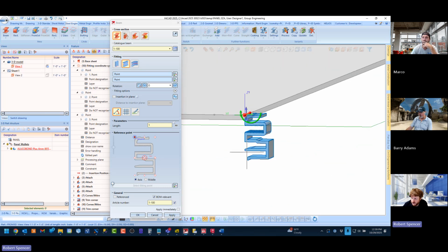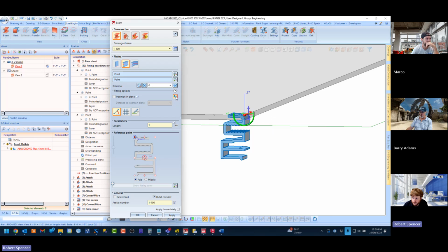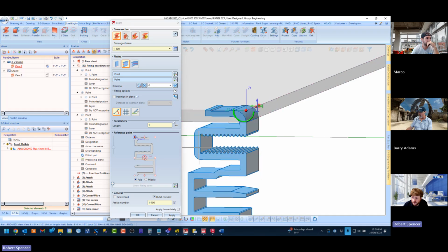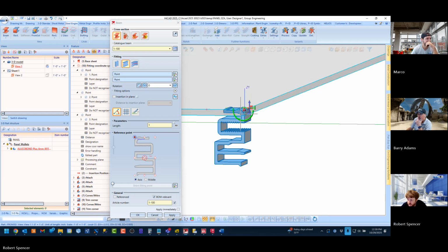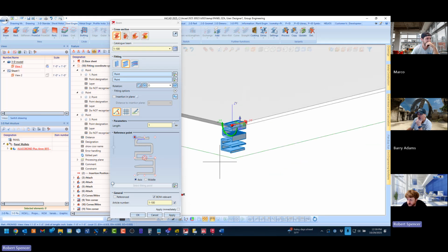And this particular profile, we actually want it to be flipped. Here with the little switch ends, you see how it then dances. We want the teeth going out because a rivet or a fastener goes in here. It's supposed to be like a drill-less attachment. This is this system's claim to fame. So how do you flip it? Switch ends, these little arrows. Oh, okay, I see. And once you're good with that, you can middle mouse or OK.